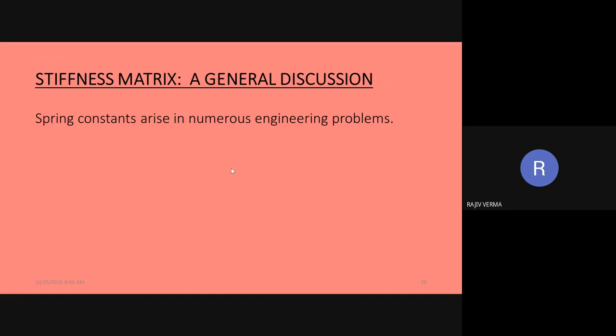But the stiffness matrix is only a terminology which in fact should be interpreted as a mathematical relationship existing between nodal degrees of freedom and the corresponding disturbing parameters acting on the nodes.